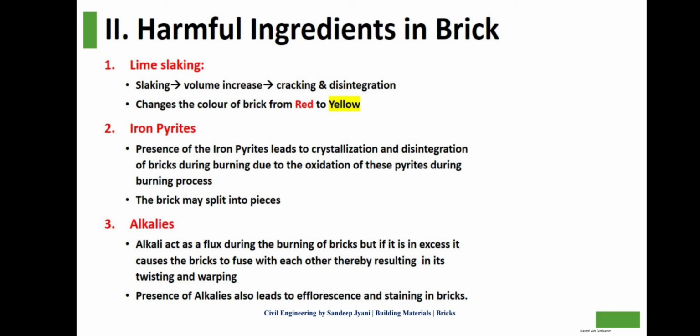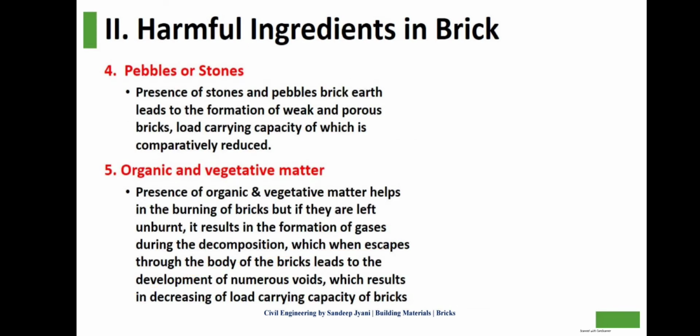Alkalis act as a flux during the burning of bricks, but if they are in excess, they cause the bricks to fuse with each other, thereby resulting in twisting and warping. Presence of alkalis also leads to efflorescence and staining in bricks. Pebbles or stones.